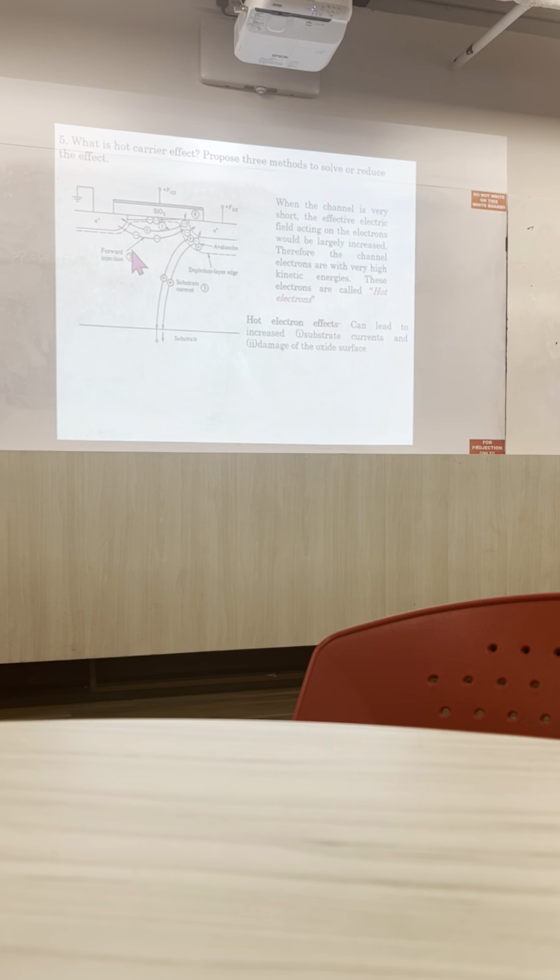LDD. LDD is the process way of doing it. Okay. So the other way is to go towards different conditions where the operating voltage is lesser. So standard is to go to 5 volt, the conventional, but then now we have circuitry with 3.3 volts, 2.5 volts, etc. But again you can see it does not make a dramatic difference. You are still in the same order of magnitude, right? Let's say your transistors go down 10 times, 20 times, the voltage just goes down by half. It's not so huge a difference, but people still do that because the probability of hot carrier formation goes down. Okay, so that's one way.